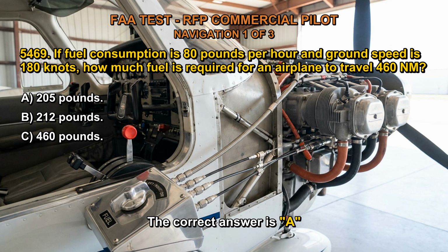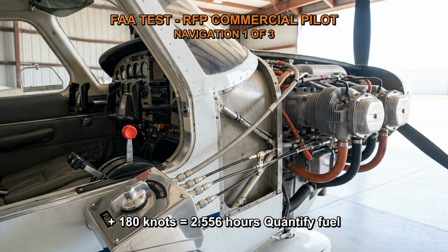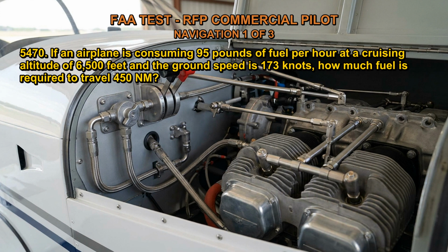The correct answer is A. Determine the travel time as follows. 460 nm divided by 180 knots equals 2.556 hours. Quantify fuel burn. 80 pounds per hour times 2.56 hours equals 204.8 pounds.